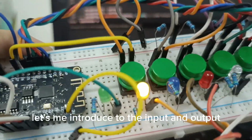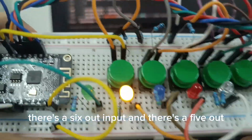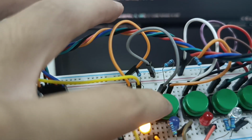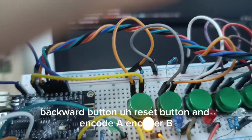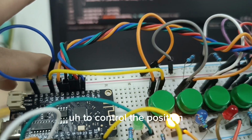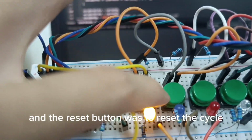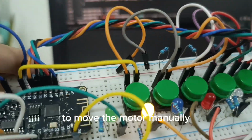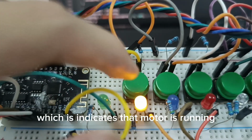Okay, let's introduce the inputs and outputs. There are 6 inputs and 5 outputs. The inputs are the start button, forward button, backward button, reset button, encoder A and encoder B. We use encoder A and encoder B to control the position, the start button is to start the motor, the reset button is to reset the cycle, and the forward and backward buttons are to move the motor manually, in jog mode.